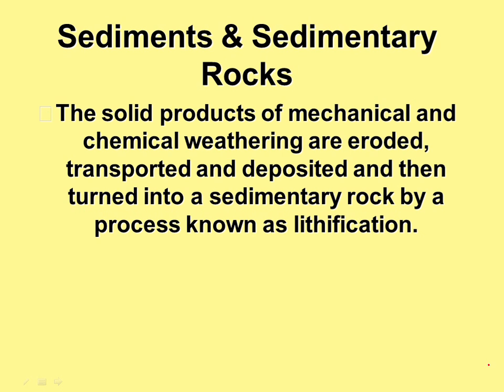So there's your compaction. The cementation obviously relates to the interstitial fluids that exist between the individual particles. If those fluids become saturated with respect to, say, calcium carbonate, the calcium carbonate can precipitate out of solution onto the surface of the grains or particles and then bind them together, the cementation process.